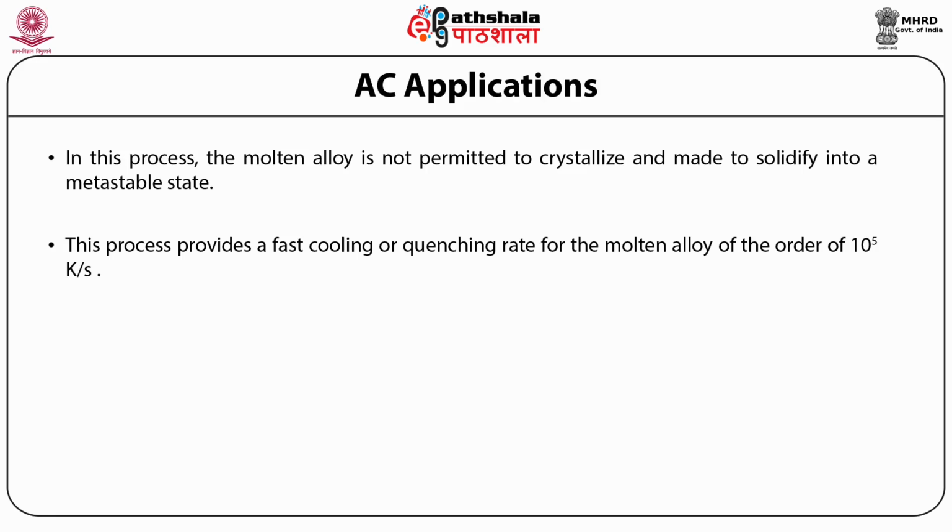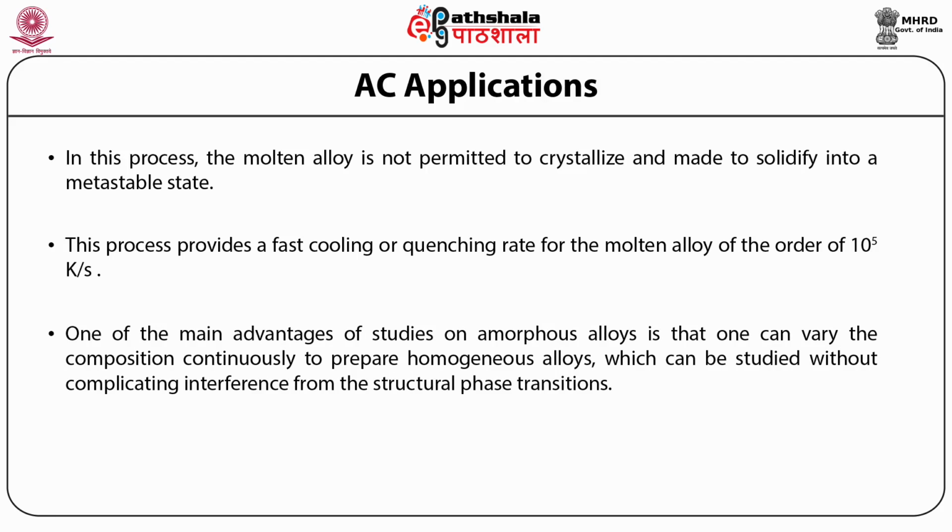On the other hand, mechanical alloying technique is a complex process involving deformation, fragmentation, cold welding, and micro-diffusion of elements in the solid state in a highly energetic grinding media. One of the main advantages of studies on amorphous alloy is that one can vary the composition continuously to prepare homogeneous alloys, which can be studied without complicating interference from the structural phase transitions.